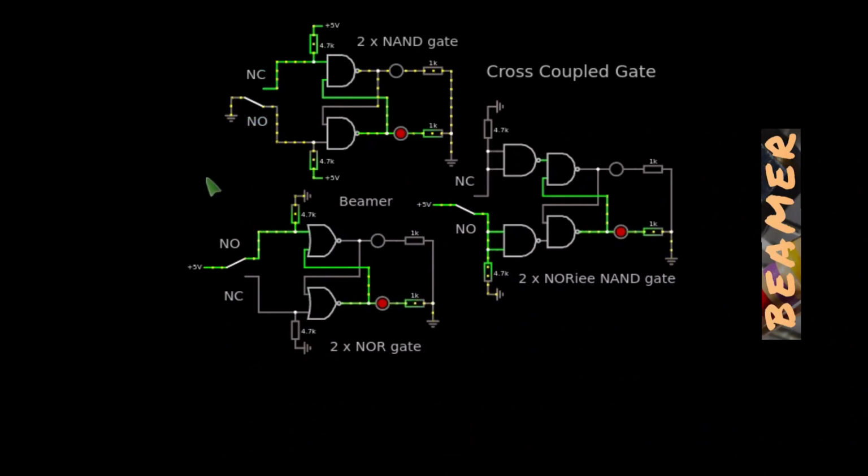Okay, so let's move on now to the NOR gate implementation of this logic. You first see that the difference here is subtle, in that instead of having pull up resistors, we've now got pull down resistors, and the wiper of the micro switch is now at +5. So if we go quickly through this logic, as that's at +5 there, that puts that at +5 there.